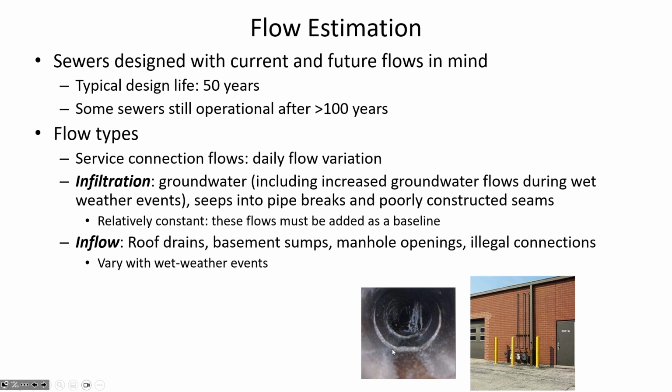So here in the picture you can see a crack in the pipe and water kind of streaming in around the seam. And then this is a picture of a roof drain where instead of discharging the stormwater onto the surface of the parking lot, it's going down and connecting into the sewer. And so that's adding flow to the pipe,